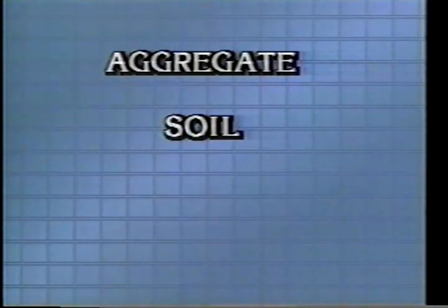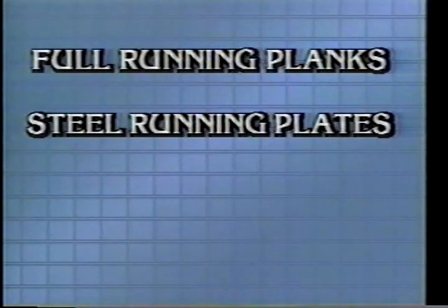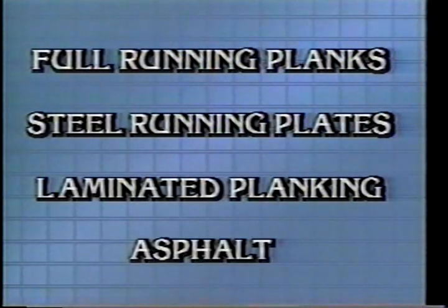The different materials that we use are aggregate, native soil, timber running planks, full-width running planks, steel running plates, actual laminated decking, asphalt, such as asphalt pavements or chip seals, and other innovative types. All of the above wearing surface treatments are effective depending on the traffic types and the maintenance that is used to treat the bridge.